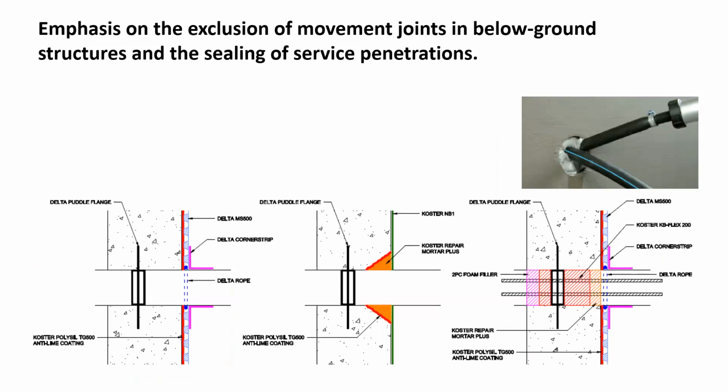Service penetrations. So in our new build basement, there's a propensity for follow-on trades to come along and put holes through your beautiful waterproofing system because they forgot to put a duct in or something like that, you know, and you'll never know about it until the building leaks.